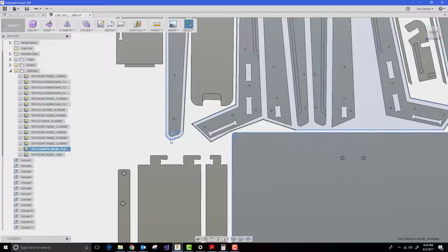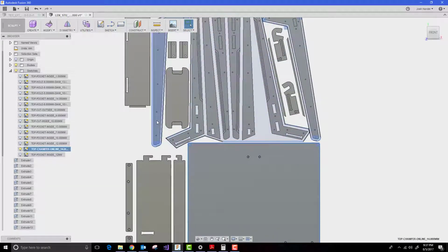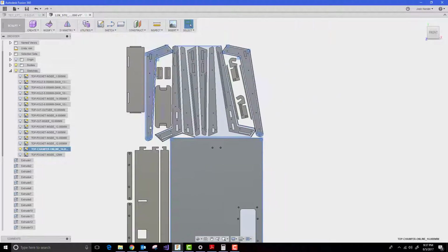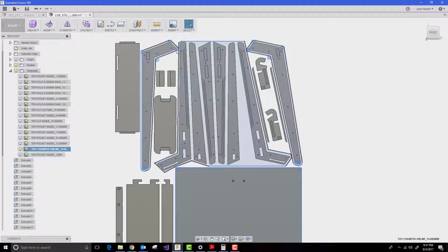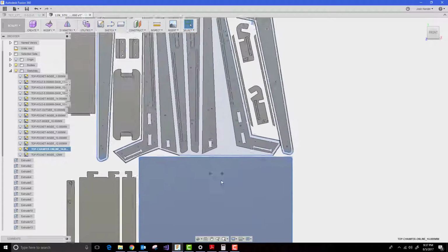Easy enough. You can do a V-bit and put it on a path, and they want that path to be 14mm down. So they've kind of pre-planned a little bit. Their estimation is 14mm down here. It's going to do just the right amount of knocking off corners. To be honest, I'm not sure why they're knocking off those corners, but they are because they're inside corners. But they're asking for it. Until I build this one, I couldn't tell you what the logic is there.